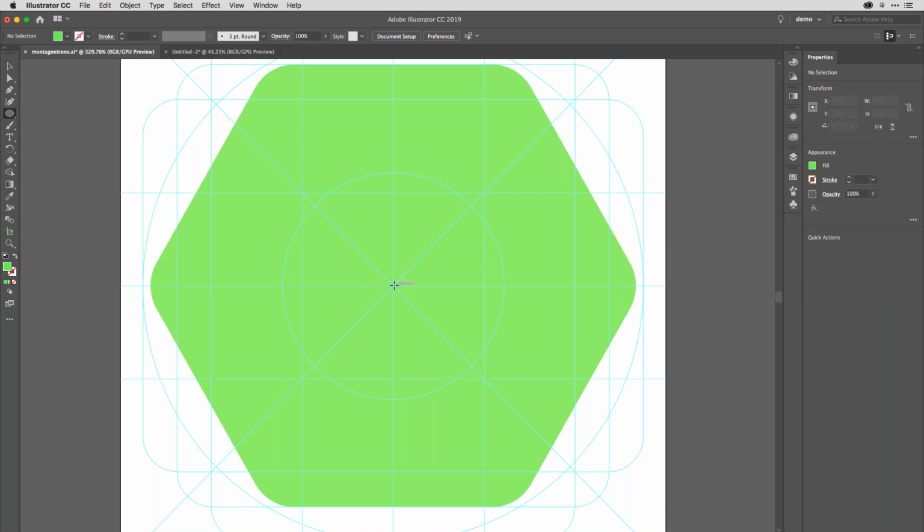are on, which you toggle by using Command U or Control U. I'm going to draw from the center outwards. So I'm holding down the Alt key, Option key rather, on my Mac. That would be Alt on Windows, and Shift combined to get a regular shape from the center outwards. I'm going to go around just under halfway of the size that I've currently got there.